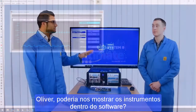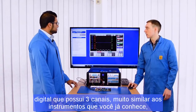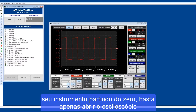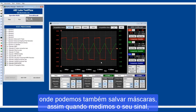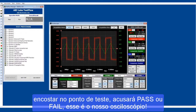Oliver, can you show us the instruments in the software? Absolutely. So in this step of our test flow, I'll open up the oscilloscope. There it is. It's got 3 channels. It's very similar to all the instruments you know, and unlike other products, it's all built in, so you don't need to create your instrument from scratch. You can just open the instrument and you've got your oscilloscope from the get-go. We've got 3 channels, as I mentioned, and you can also store a mask. So when you measure your signal, you can then click Save and Store, and it'll store that mask that you can then compare against later. We're a big fan of pass and fail, so when you probe that mask again, it'll either give you a match or not a match, a pass or a fail.